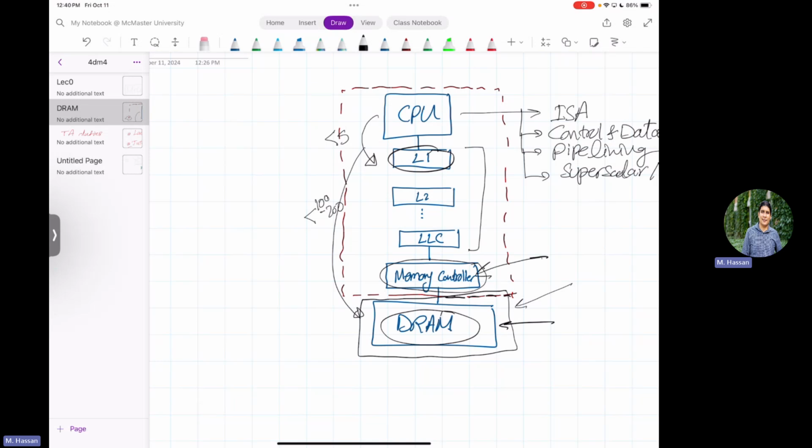So there is another on-chip module that is the brain of handling the main memory system: it schedules accesses, maintains DRAM state, and we'll now discuss the details of the memory controller. And in fact, your next lab is mainly about memory controllers and DRAM. So you will see how memory controller components are doing a lot of scheduling and reordering to optimize for memory access.